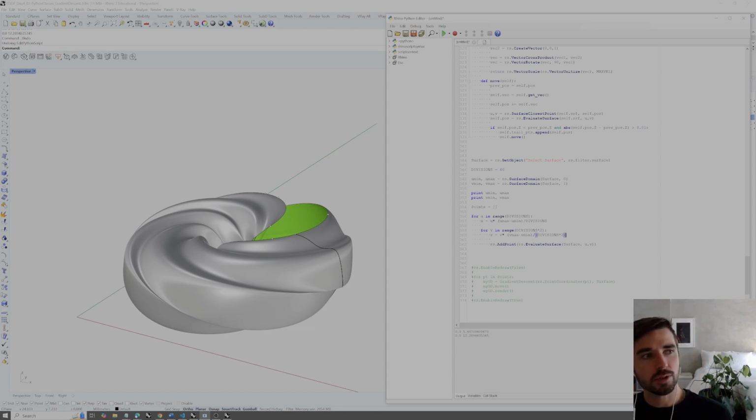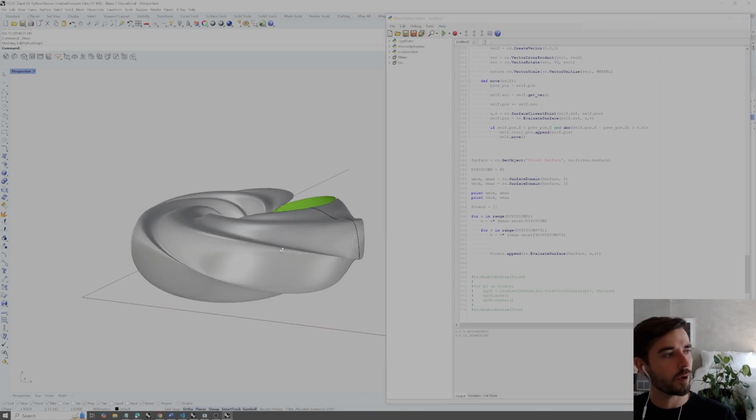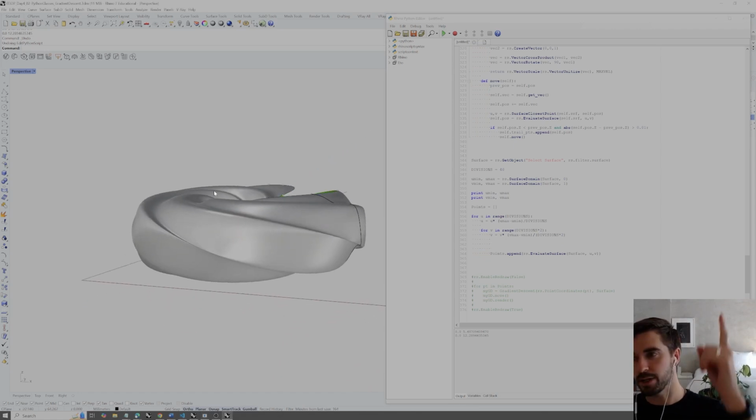So now, in order to complete this as kind of rainfall and not just draw points, first, we don't want to make the points in our document. We want to append them to this list. So we want to say points.append. Okay, so we're appending that point output to our list of points. Now, when do we want to do this? Well, we only want to do this when the surface is facing up to catch the rain.